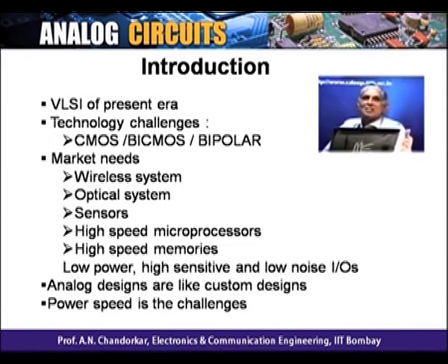It's a paradox there. Analog designers left to themselves say, okay, put 1 micron channel lengths, it's great. Whereas digital will say put 10 nanometers if you can, 11 nanometers if you can. So there is a problem, and therefore the design of integrated circuits for analog plus digital has become very, very crucial, because of bad technology, with circuit tricks so that it actually does a lot of good things even with the digital around, and that's where the challenge is.